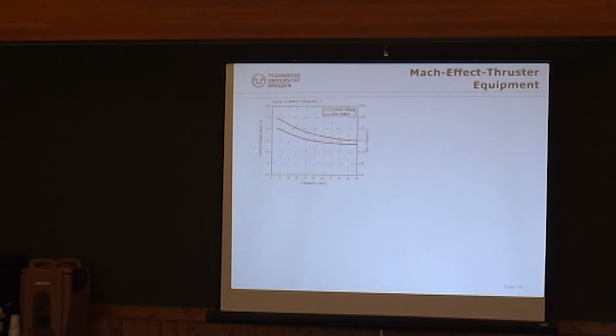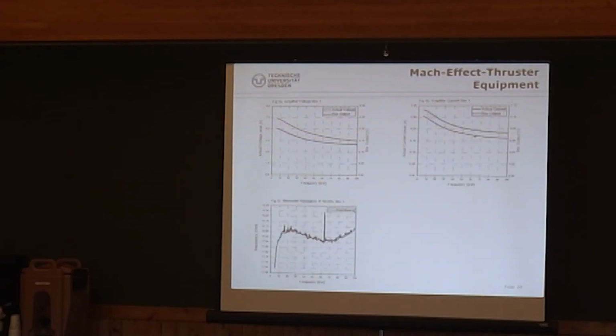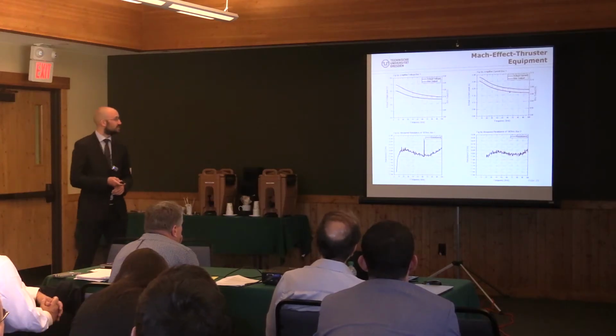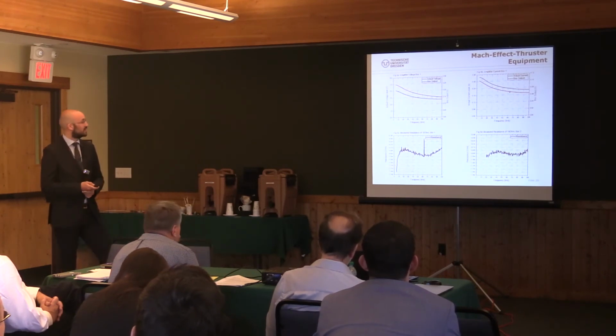So basically this is the voltage we measured with an oscilloscope, the black one. And on the right side is what the box gave us as a result. And you see there's a discrepancy. And we did the same thing for the current. And then we got an equation from that, put it into our program, and then measured the resistor again, and we got a nice 80 ohm resistance for the first box and also for the second box. So that's basically how we calibrated our two boxes, so we know they output the right thing.